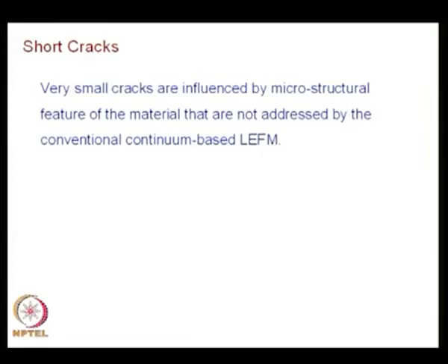So, could you please explain why in the case of short cracks or very long cracks the LEFM criteria are no longer valid, even for relatively brittle materials? Yeah, we will get into the problem of short cracks, and you have to understand how they influence. Very small cracks are influenced by microstructural features of the material that are not addressed by the conventional continuum based LEFM, because it depends on the scale.